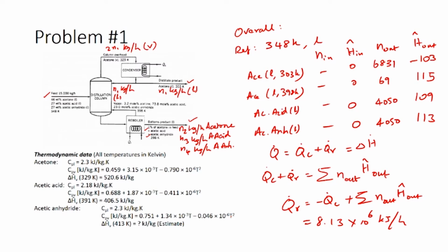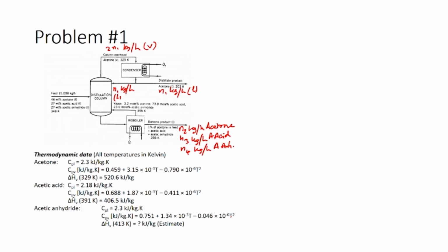Just by condensation, using the steam tables, we can identify the enthalpy associated with condensation or vaporization of saturated steam at 10 bar as 1999 kilojoules per kilogram, and so this means condensation of 1 kilogram of steam saturated at 10 bar would generate close to 2000 kilojoules of energy.